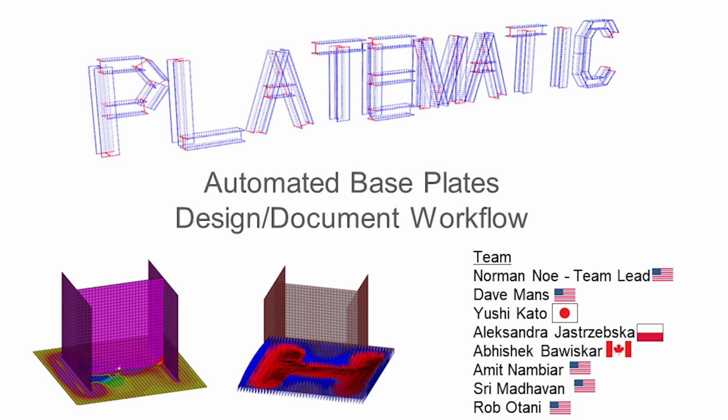I definitely think that's the future. That's what we're trying to get to. I think the structural engineering world is a little bit lagging behind a few other industries, in my opinion. The other thing is that typically in LOD 300 models, we don't model base plates. There isn't even a Revit BIM element for it. It has to be a custom component. But eventually, if we have the workflow, then we can apply the associated data to that component and populate it.